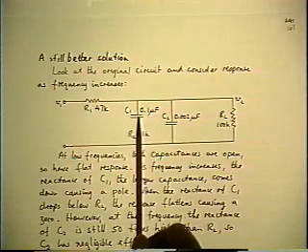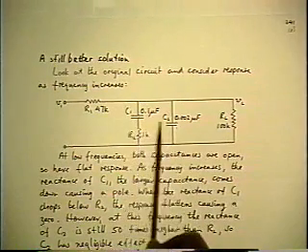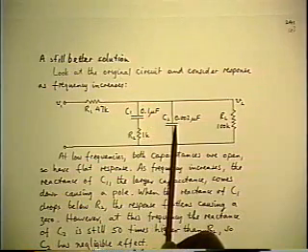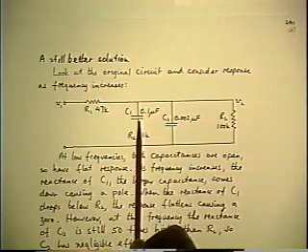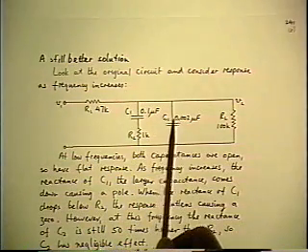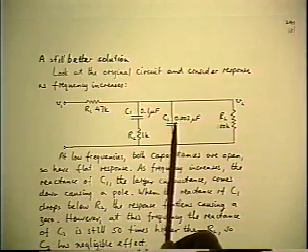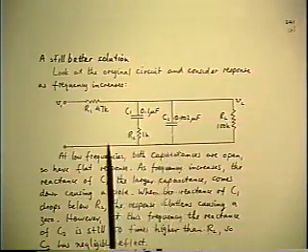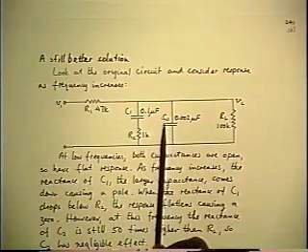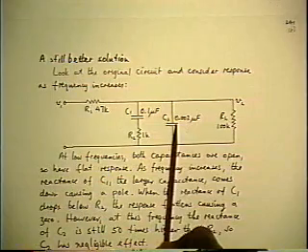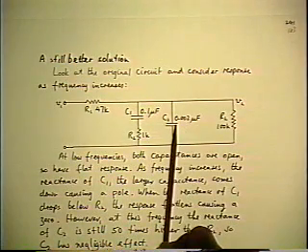As the reactance comes down, because C1 is 50 times bigger than C2, the reactance of C2 is 50 times bigger than that of C1. So even though they're effectively in parallel, the C2 isn't doing anything. So you could throw it out, which is equivalent to dumping the second part of that middle coefficient, based on the same approximation, which I already mentioned is less than a 2% error.